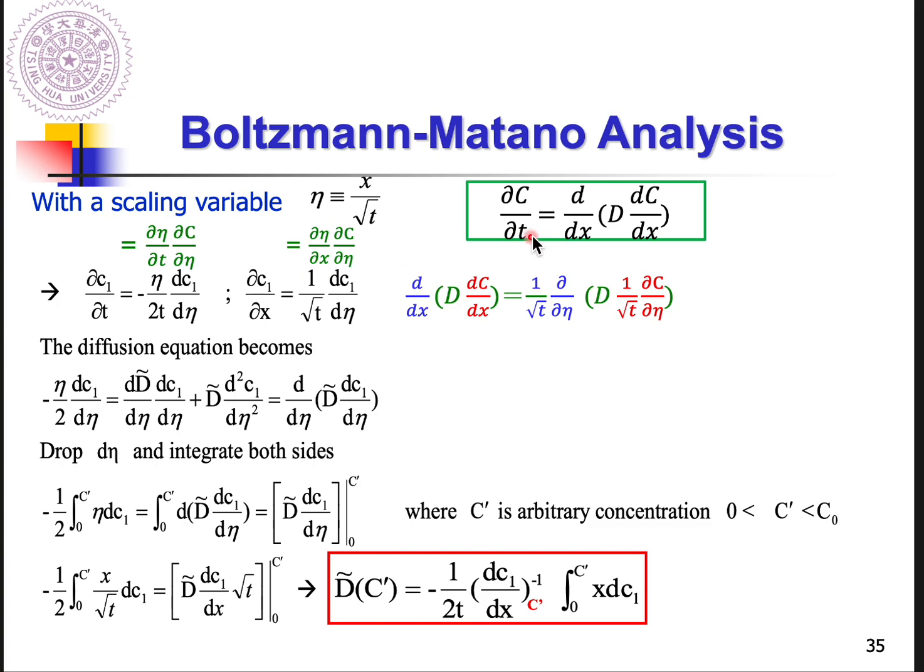And one thing you need to pay attention to would be, before you inserted these results, you need to deal with the right-handed term here, right? So I use different colors to label that. Diffusivity, partial c, partial x is what we get here. So you inserted these results, and now you get this result, right? So you need to partial this term d times partial c, partial iota. You cannot just take the diffusivity out because d is a function of c.